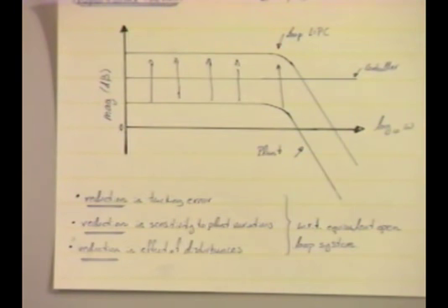So if you have proportional control and you command 40 miles an hour, if the person who designed the controller was good, they would give you the proper 40 miles an hour when the ground is steady. But suppose now you start going up a hill. With proportional control, what you're going to find is you won't go at 40 miles an hour.